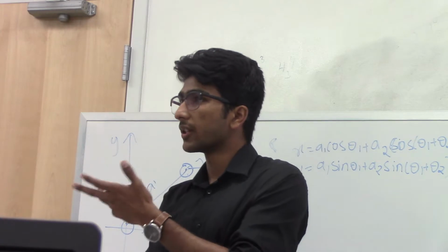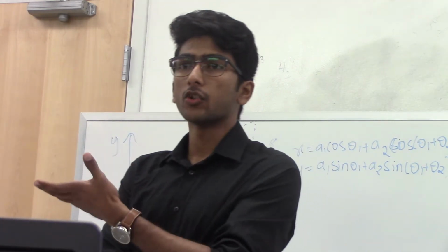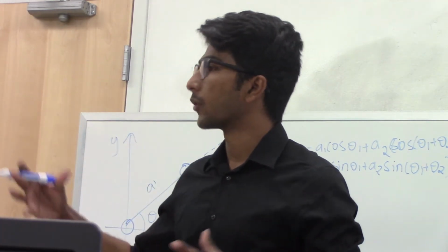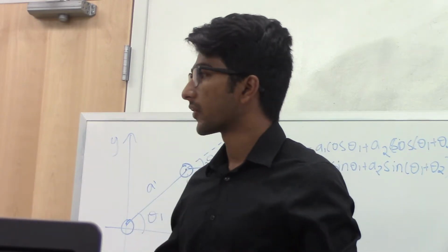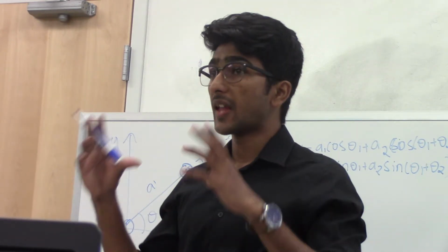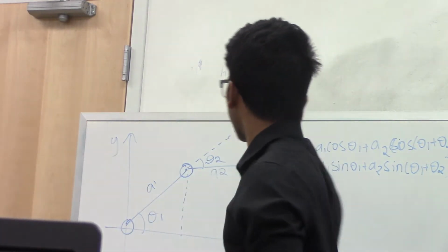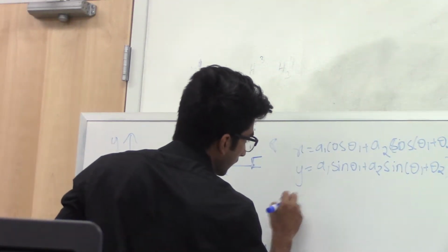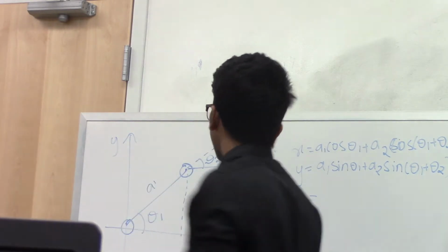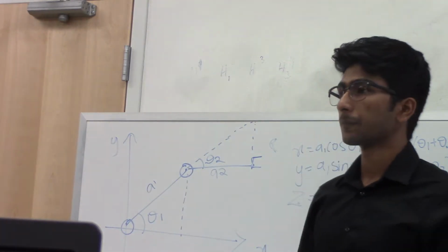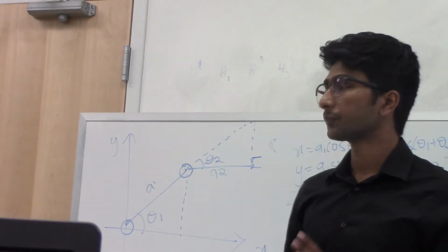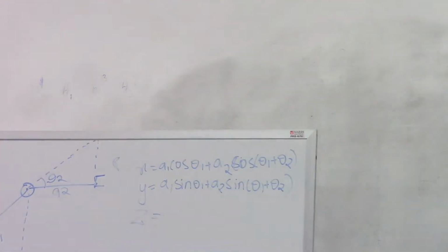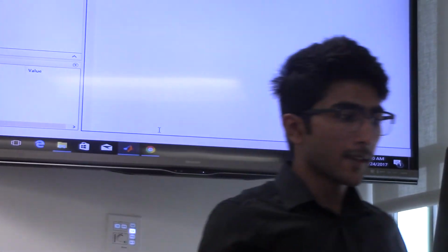Just using these 4 parameters for every joint, we can construct a rotational matrix, a homogeneous transformation matrix, and use that matrix to calculate the forward kinematics and find the x, y, and z values no matter how many joints you are given. Are we clear at this point? So let's build that using our toolbox.